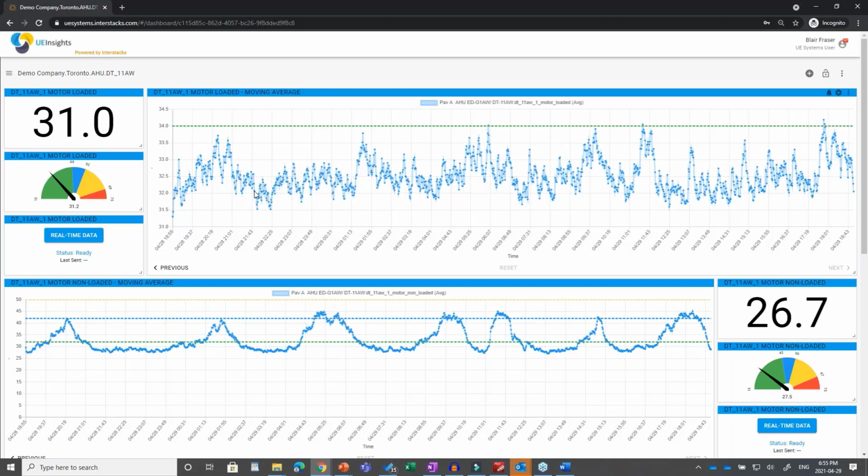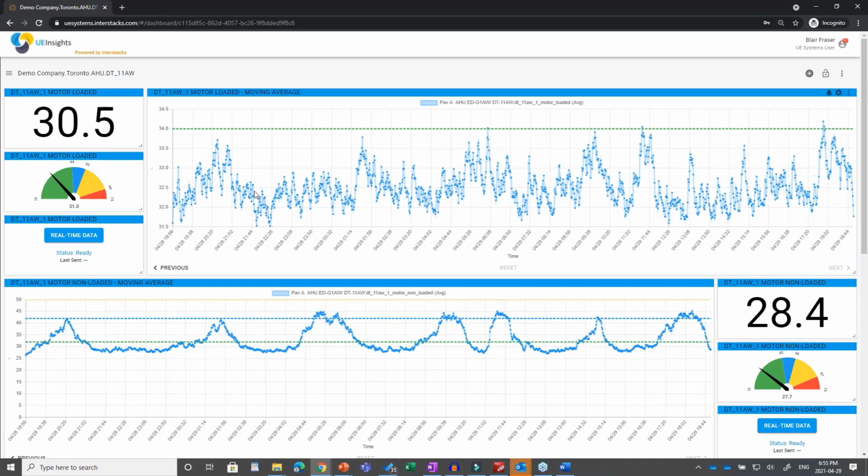So looking at this, and this is where you can pick up belt slippage and things like that, because we actually had a use case where the drive end of a motor was driving a belt that drove the fan. We saw the drive end of the motor and the corresponding end on the other belt on the fan actually impacting at the same time, and we're seeing that belt slippage come through, right? So this is how we can start to use this data from a VFD or VSD point of view.